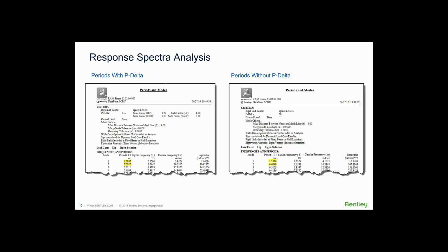If you're going to use the B2 factor, I would just do my normal analysis and then apply the B2 factor to all of them. But having said that, I'm not sure. Now that I think about it, you could just apply the B2 factor to the response spectra analysis case. You wouldn't apply it to your dead and live because you already took those into account. I suppose you could do that. I haven't done that, so I'm hesitant to endorse that one way or the other.